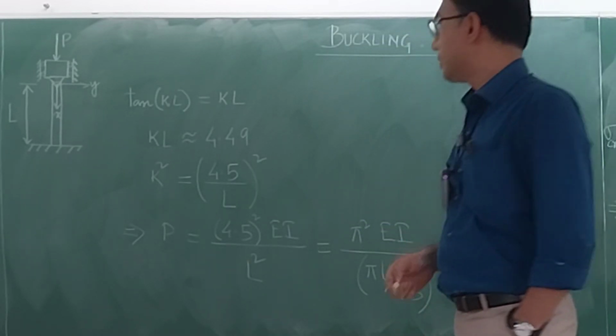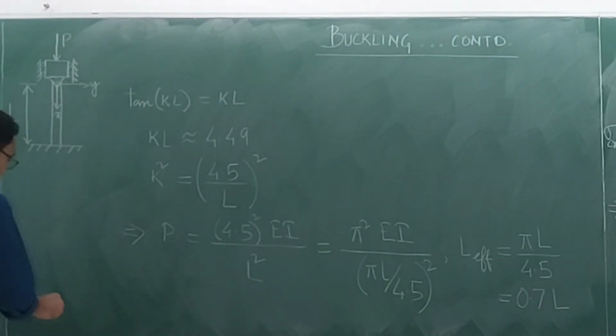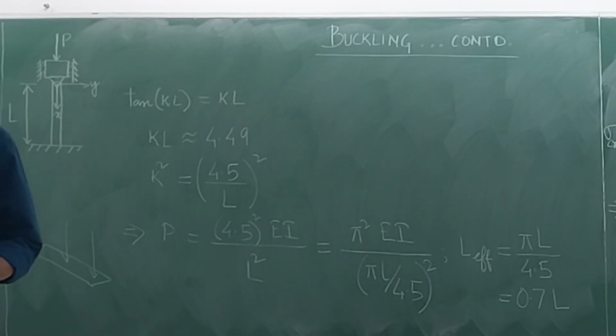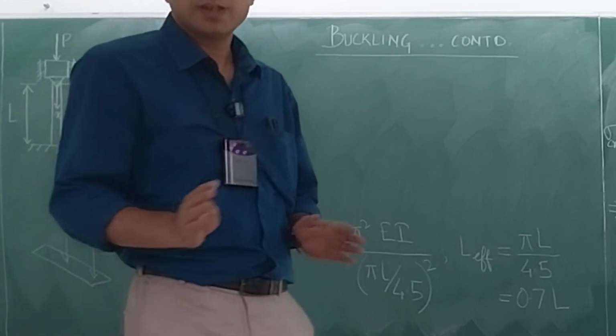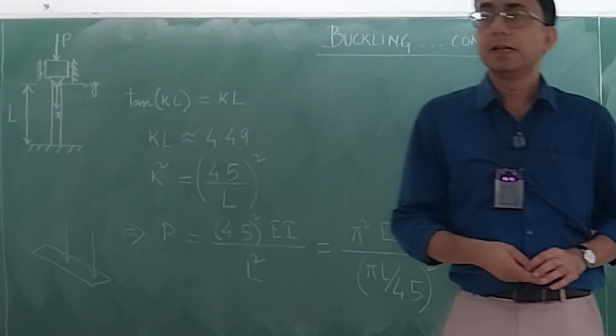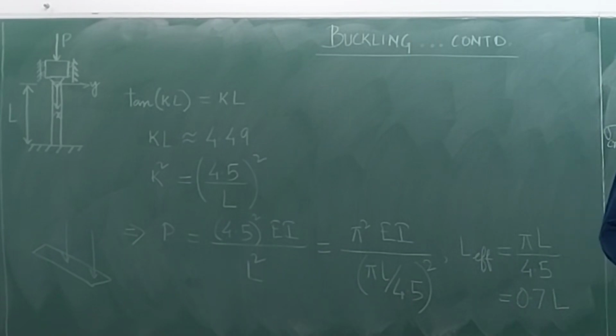So see, the situation is something like this, that if you have a cross section which is like this, okay, this is the center. All our cases will be like this, where it is through the center. But suppose you have a force like this, then in addition to the axial loading, you are also going to end up with a non-zero bending moment. So it is a simultaneous case of an axial load and a bending moment. The way to address those things is a little bit different. It can be done. If you're really interested, you can take a look in Beer and Johnson. They have done it, but not in very much proper detail.